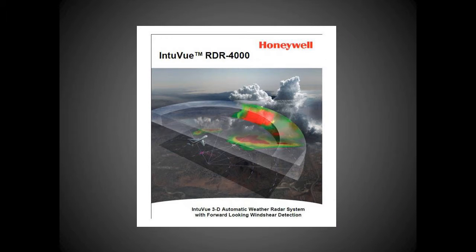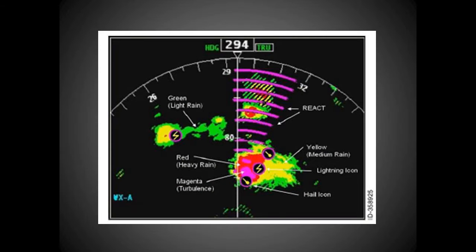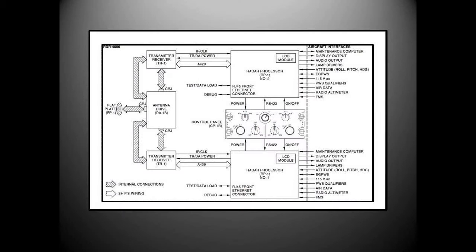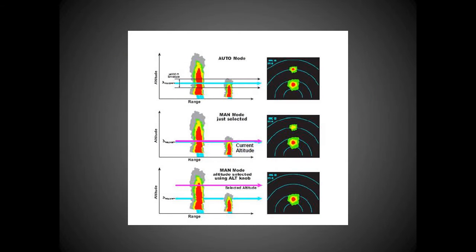Given the complexity of the RDR-4000, misdiagnosis of flight deck effects often results in no fault found, or NFF, outcome of shop repair activities. Troubleshooting this system is simple when using the front panel LCD display on the radar processor. Follow these steps to interrogate the radar processor's fault memory to determine the faults that occurred during the previous flight legs or during ground operations.